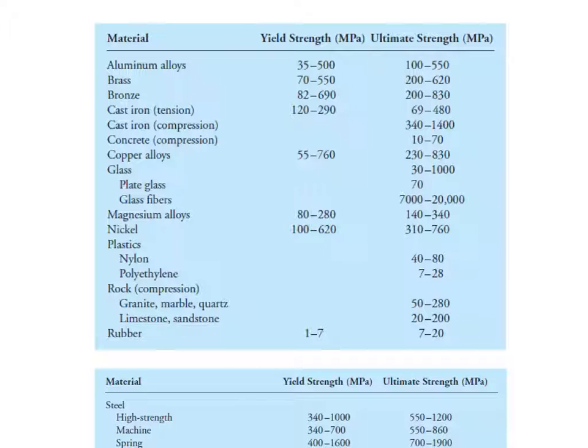So a material yields for some time under stress. It's kind of interesting. You start to apply a certain amount of force to something, it will start to bend and bend and bend, and it will start to yield, and you saw this with your boom lever. Johnny, was it yours that really bent a lot on the bottom? Theirs was yielding for a long time. It started to really bow out. Those are things that you don't want to happen to structures that you'd be walking over. But it yielded for a while until, actually no, it never reached its ultimate strength. The glue at the top is where it separated. So the bottom that was yielding, that was bending, never reached the ultimate strength and it never actually failed.